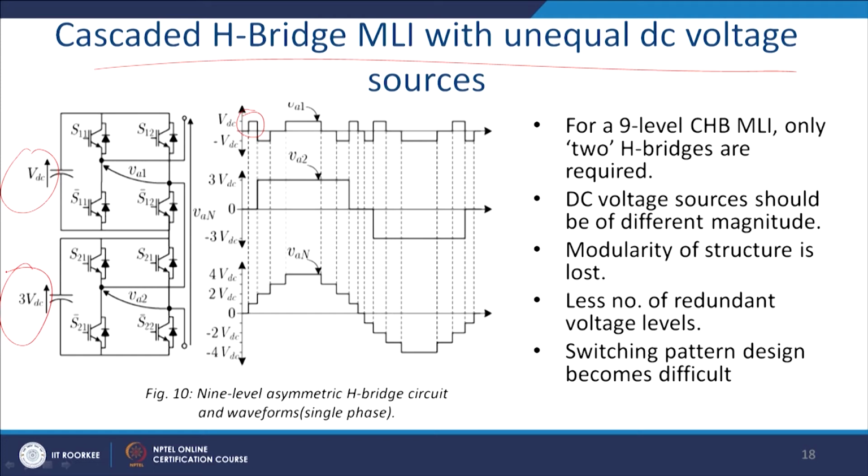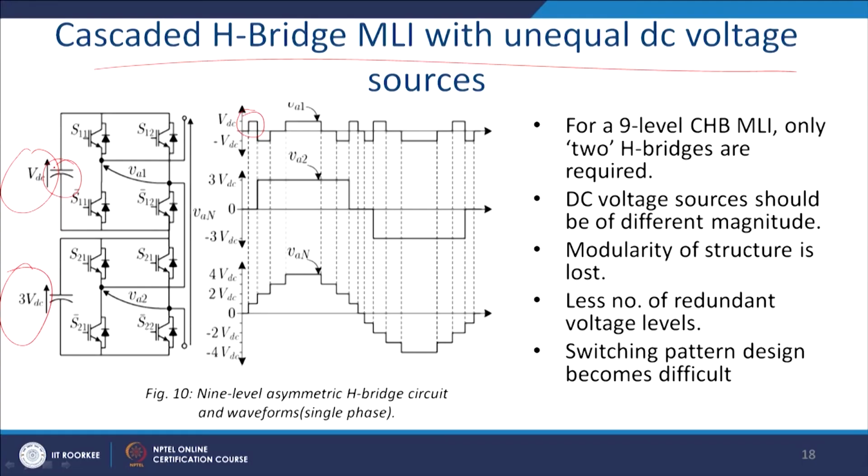It can be a shunt active power filter, and instead of the capacitor you can keep this capacitor voltage at that level by actively controlling it in the case of the shunt active power filter, and you can do it also by putting in a solar panel.